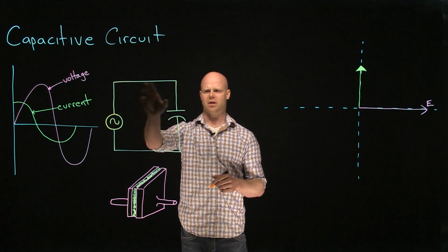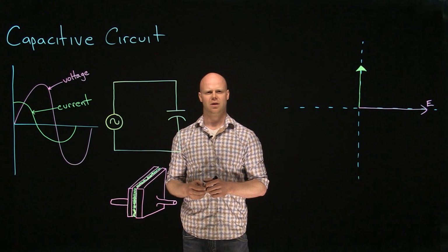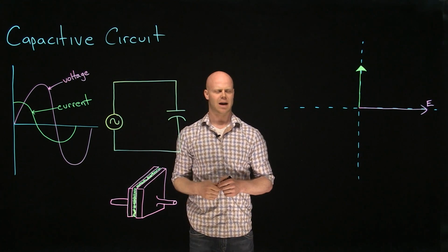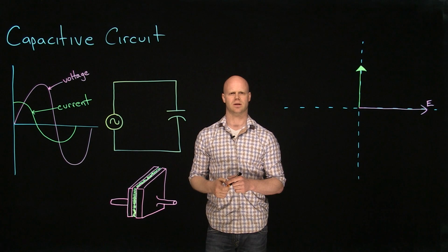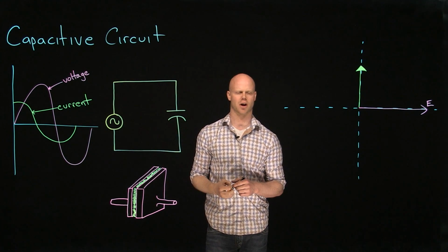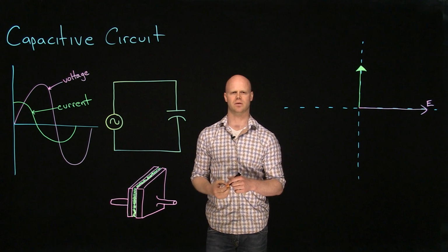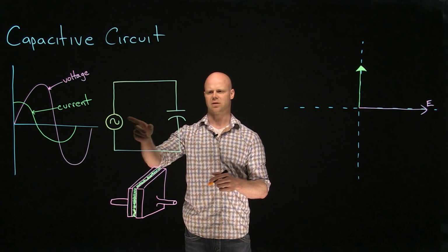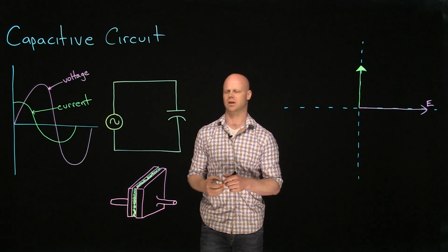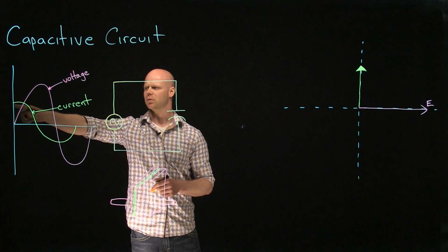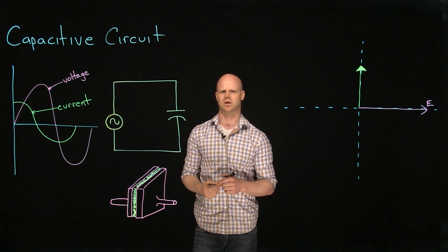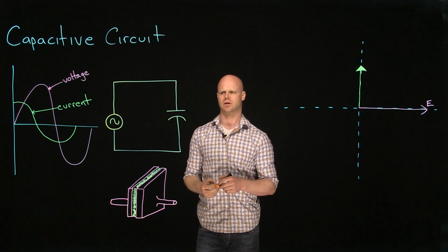So at the point of energization on my electrical circuit, theoretically there is no opposition between my source and that capacitor. Because there's no opposition between those points, there's nothing opposing current from reaching its maximum value instantaneously. So what we have is that current rising to its maximum value instantaneously, which is represented here. We see at the first moment in time, current is at a maximum before that capacitor is charged.